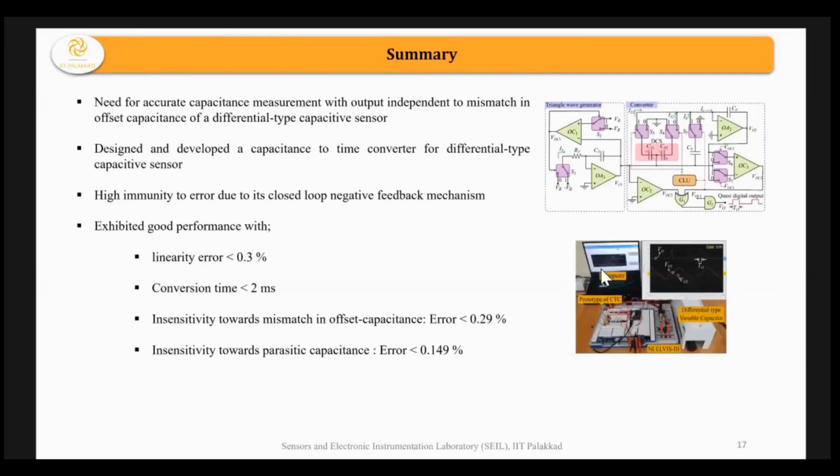Let me summarize the work. There are many measurement circuits, but in the proposed circuit we have overcome some of the challenges, like offset mismatch nullification. It implements a fast measurement circuit whose output is a pulse width modulated output, where the pulse width is proportional to the change in capacitance delta C. It was developed in the institute, and we could get a good performance.